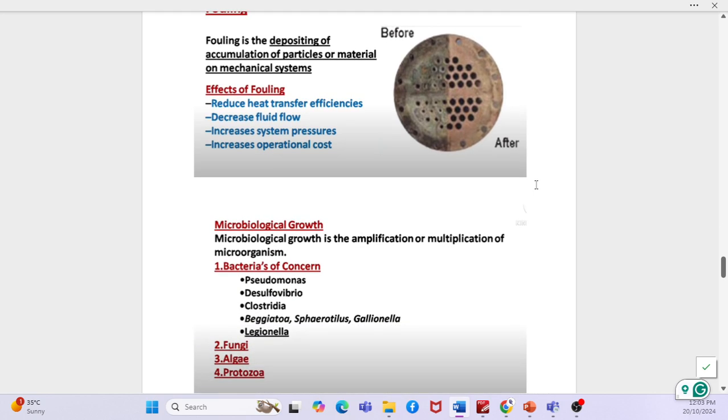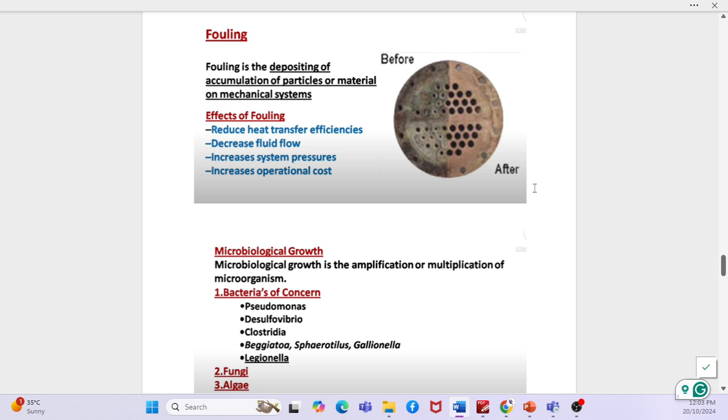Sir, I have one question. Yes, tell me. Regarding this fouling, now we are using a ball system. Small balls come through, connected with the main return, go to the chillers, and remove the corrosion and deposits. Oh, like balls that clean the system inside. Yes, small balls. I will send the video, because we already installed one. What will happen?